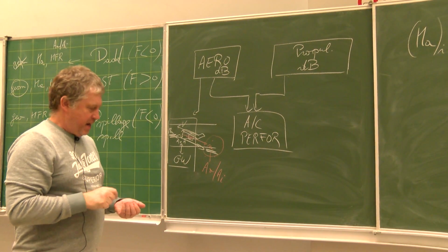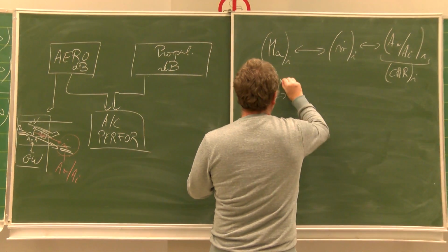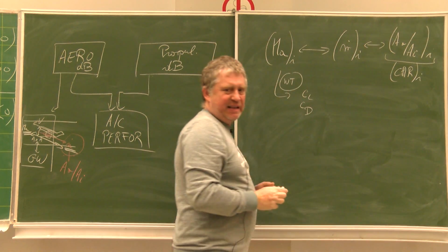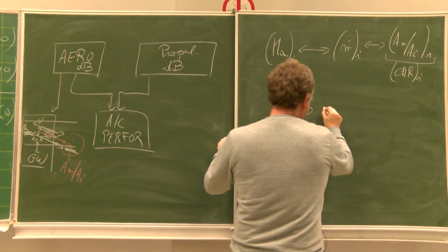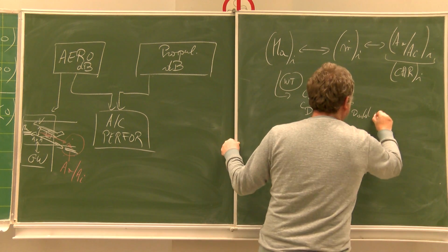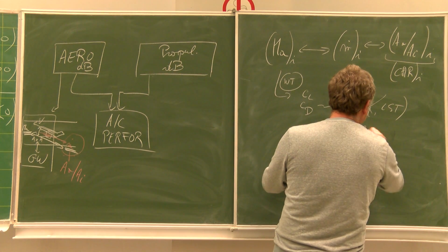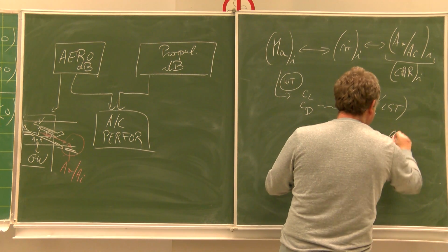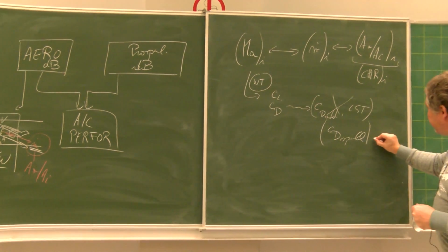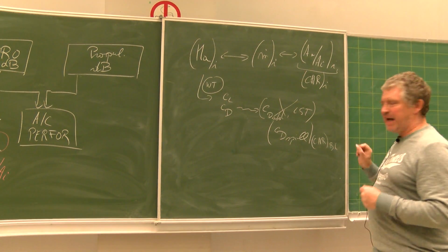And so they go to the wind tunnel, and in the CL and in the CD that they are obtaining, in fact, this CD is containing the CD additive and the lip suction thrust. So it's containing, in fact, the CD spillage for what they call the capture area ratio baseline.